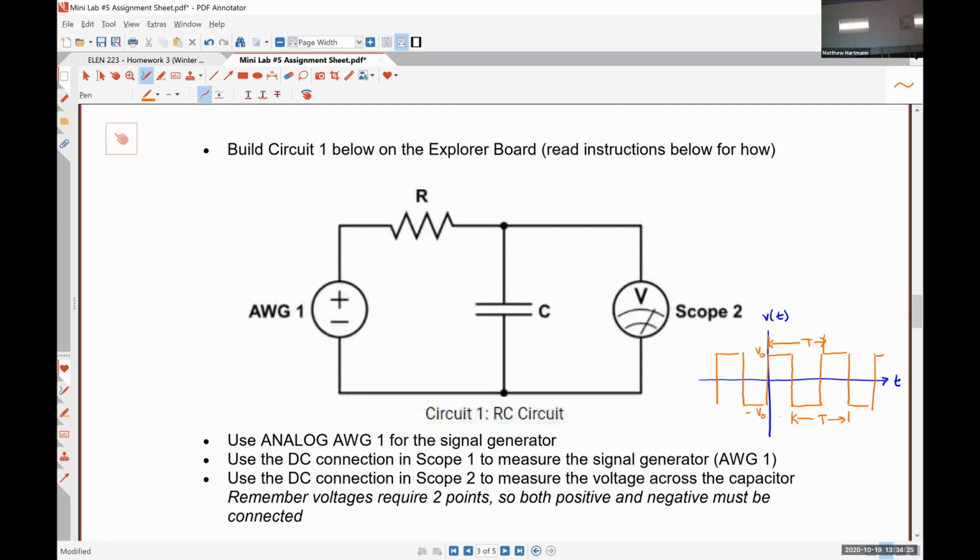And what I mean by that is that every time we see our voltage signal change from positive to negative or negative to positive, that's a new operation of effectively us opening or closing a switch, all right? So the key here is to use a frequency such that we allow the signal enough time to decay, right?